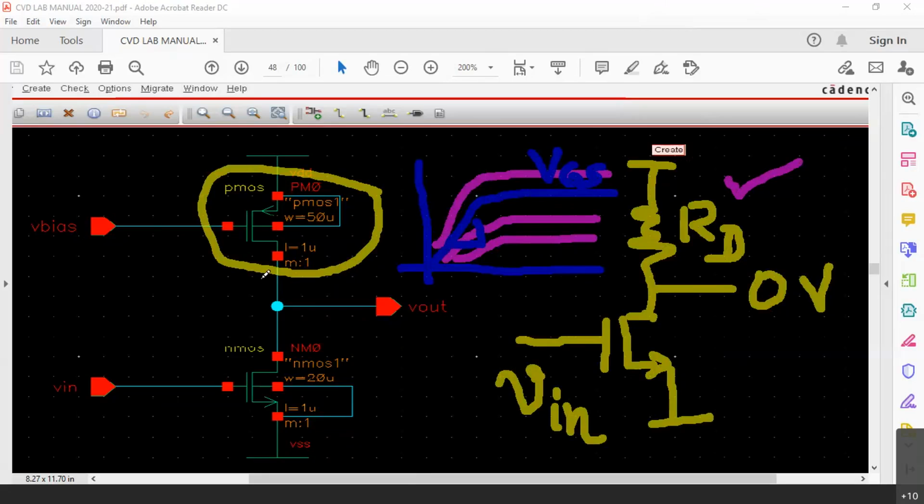So for the first question, the answer is: a resistor can be replaced with the transistor when the transistor is operating in the linear region or the ohmic region by applying a requisite gate to source voltage. That is where we keep on telling MOSFET is a voltage control device. By means of a voltage, we can control its switching operations. This is the first question.